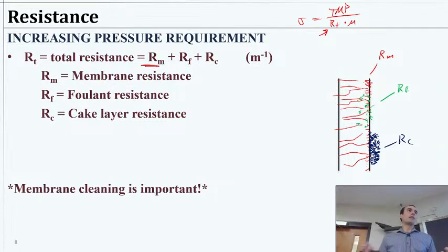to clean our membranes. In real operation, we will tend to clean the membranes quite frequently. For example, there's an application called membrane bioreactors for wastewater treatment, and you'll actually stop the membranes just really briefly. It's an automated system, and you backwash for like a second, just pulse a little bit of water backwards through them, like every minute or something. Or you'll apply some vibrational shaking every couple minutes. So there are these techniques you can use just to try to get the fouling layer off as much as you can.